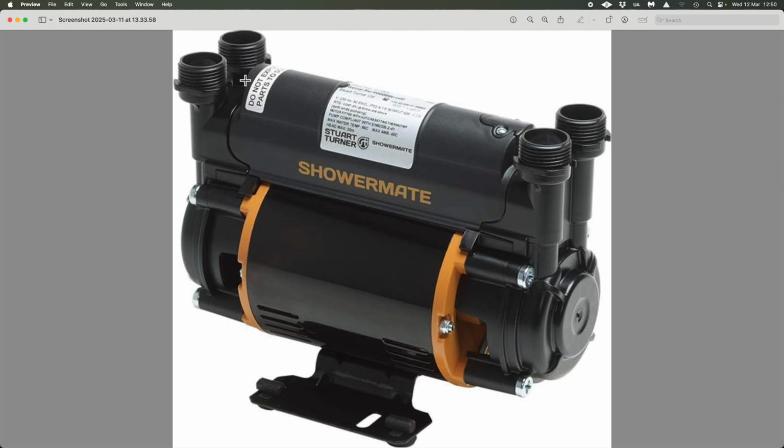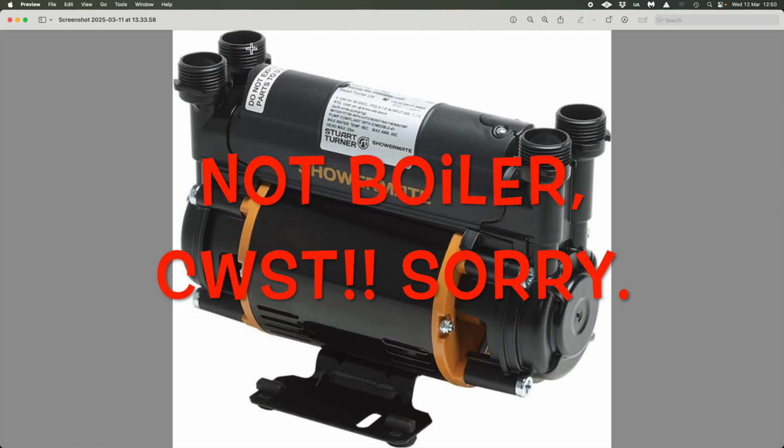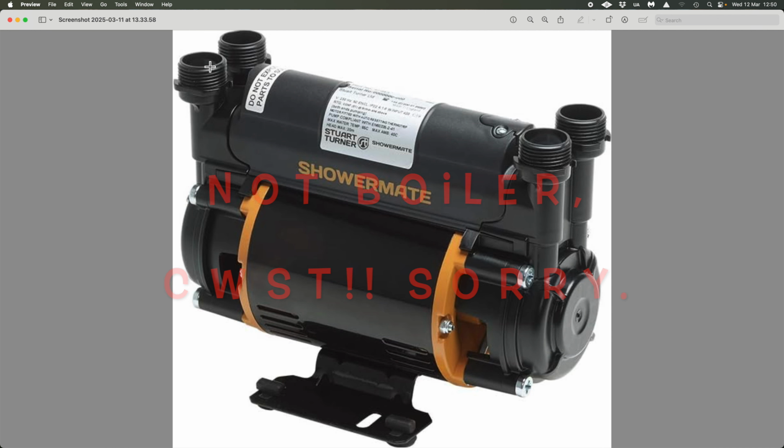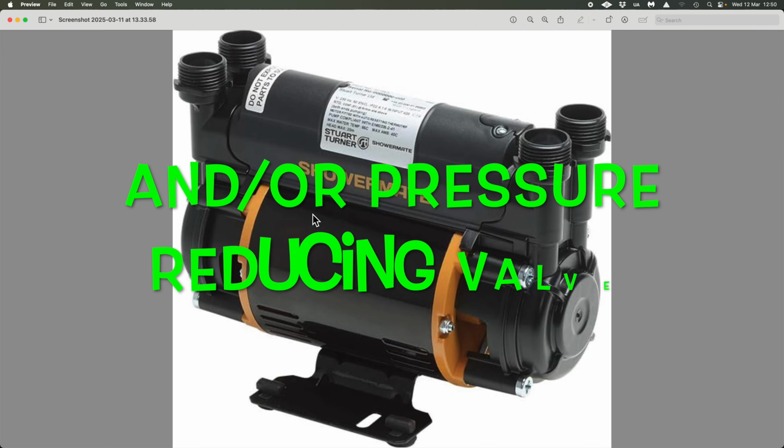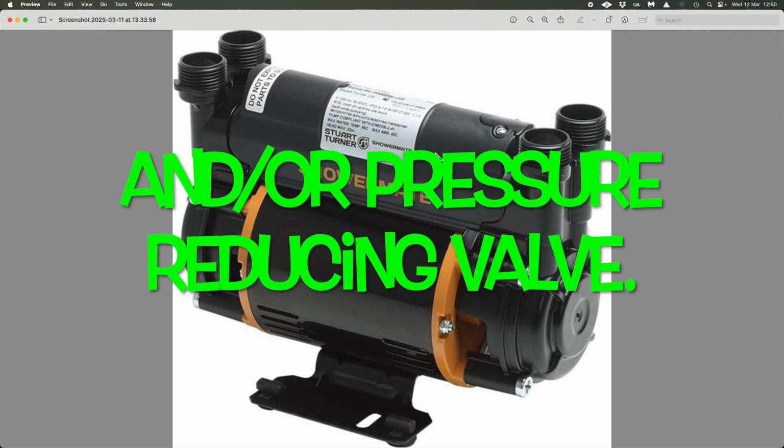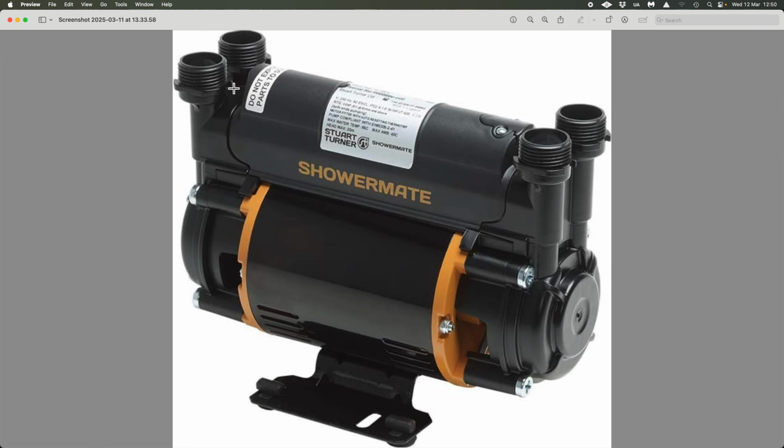And then the other side of the boiler would literally come straight out of this side, and that would go to your cold taps. And if you wanted to, you could put a double regulating valve on that to make sure that you've got balanced pressures coming out of your taps downstream, which again is something that I would recommend to be done. This opens up this whole thing, and it balances your hot water system so you get it correct.